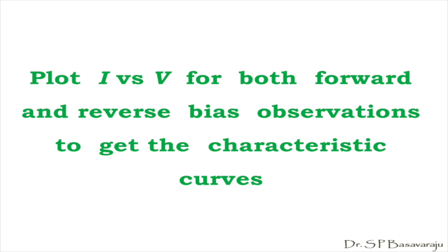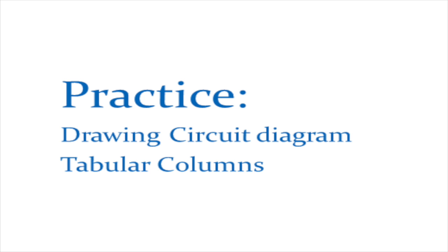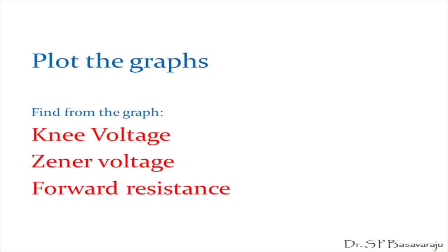That's all about the experiment. As preparation for the examination, you must practice drawing the circuit diagram and tabular columns. Also, plot the graph by taking the values from your practical record. Further, find out the knee voltage, Zener voltage and forward resistance from the graph.